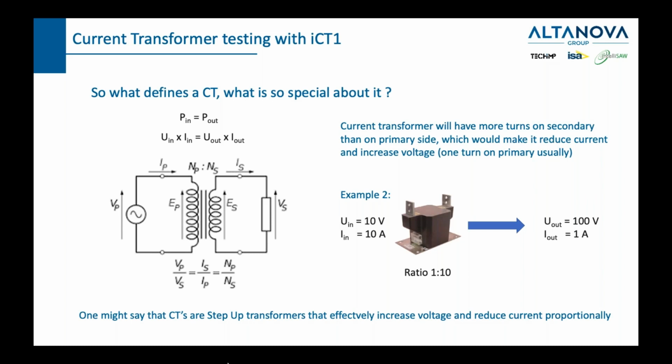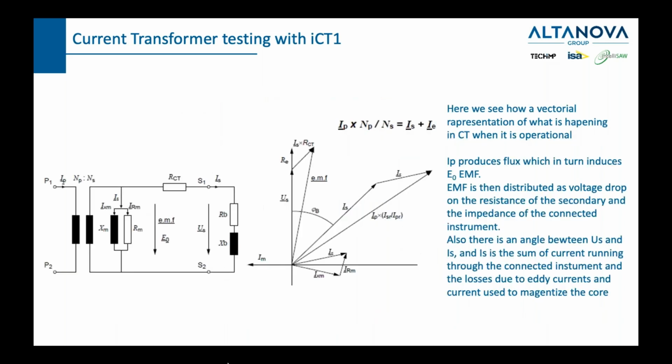The point is that we always want to have, for a certain type of CTs, on the secondary side what we have on the primary side correctly transformed, but in some other cases we don't want to transform after a certain value, because we want to protect certain devices. So after explaining all this, let us become a little bit more technical.